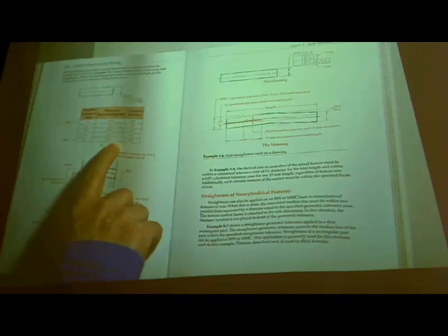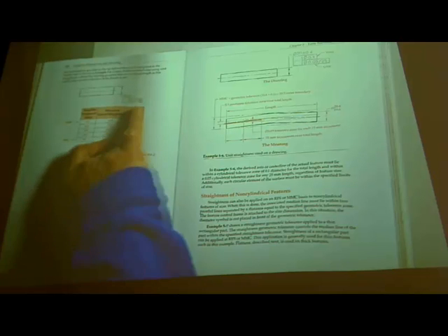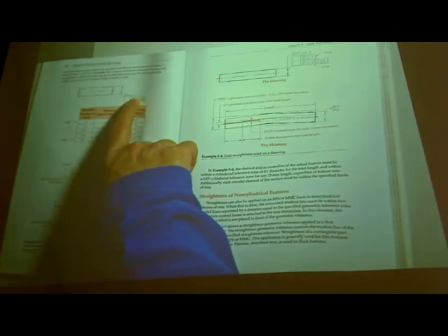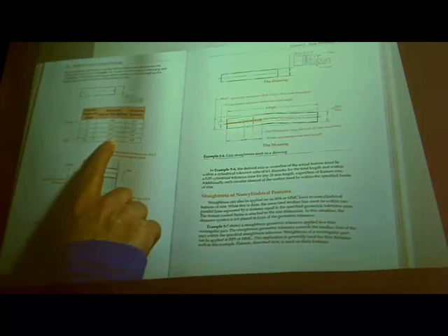Okay, so here we are at 0.45. So plus or minus 0.2. You know, so 0.4 is the tolerance on the size, but the out of straightness is actually becoming larger. So something, you know, that may be really unacceptable if it's applied that way.